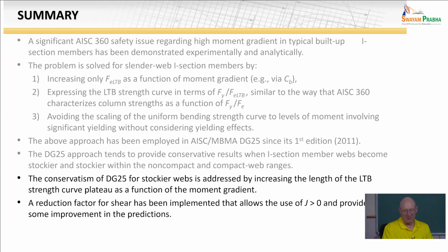I think it's fair to say that the Eurocode results are giving adequate predictions; generally they tend to be conservative to accurate, and the Eurocode is not using a shear reduction factor. But the American code tends to base our elastic LTB resistance on a theoretical elastic buckling. So I think we're a bit more on edge there with the way we do the calculation.